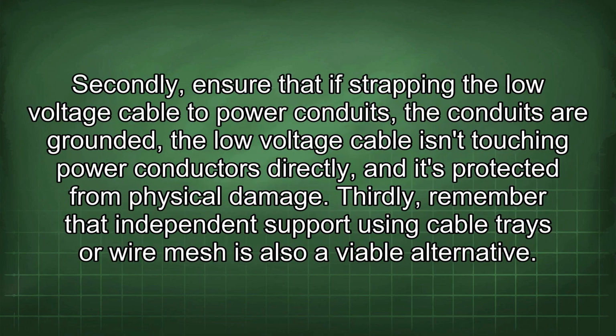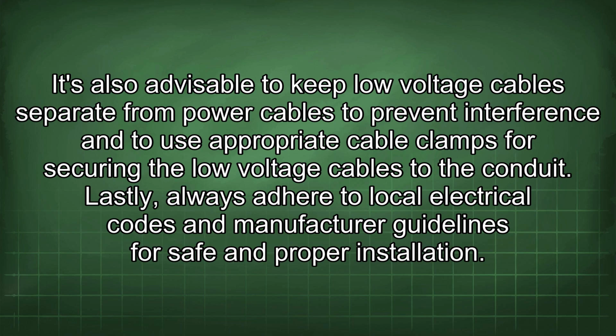Secondly, ensure that if strapping the low voltage cable to power conduits, the conduits are grounded, the low voltage cable isn't touching power conductors directly, and it's protected from physical damage. Thirdly, remember that independent support using cable trays or wire mesh is also a viable alternative. It's also advisable to keep low voltage cables separate from power cables to prevent interference and to use appropriate cable clamps for securing the low voltage cables to the conduit. Lastly, always adhere to local electrical codes and manufacturer guidelines for safe and proper installation.